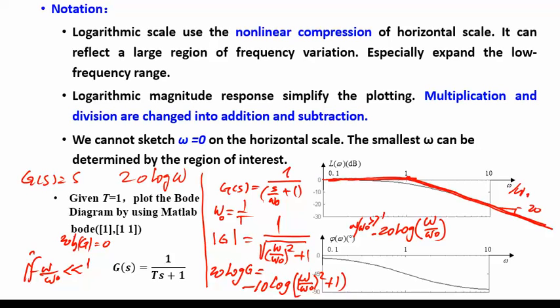So with this one you make an error of 5 degrees. So this starts from 0, and it goes to when omega over omega 0 is large. What is tan inverse of a large quantity? 90 with a minus sign, minus 90. So the phase angle goes from 0 to minus 90.